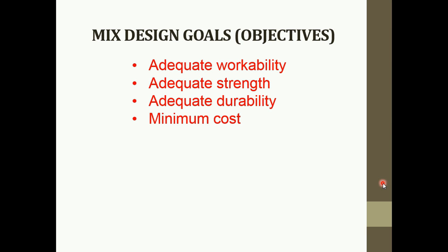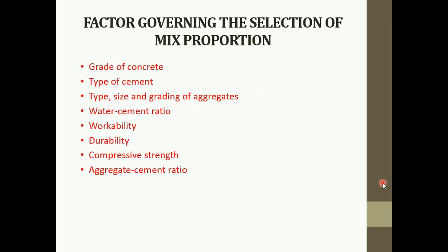The factors governing the selection of mix depend on the grade of concrete that we are going to produce, type of cement, type, size and grading of aggregates, water cement ratio, workability, durability, compressive strength, and also the aggregate cement ratio.